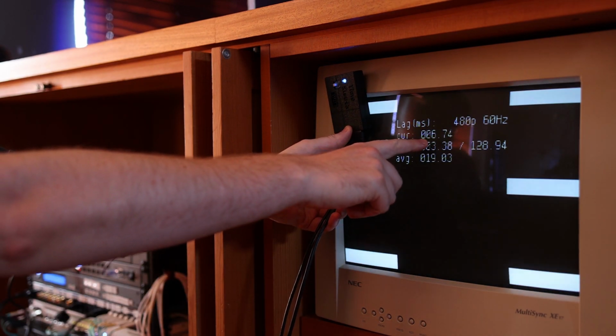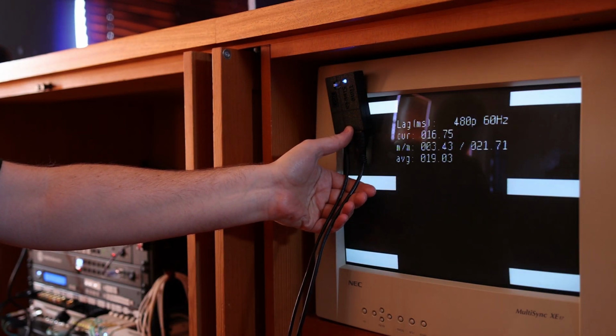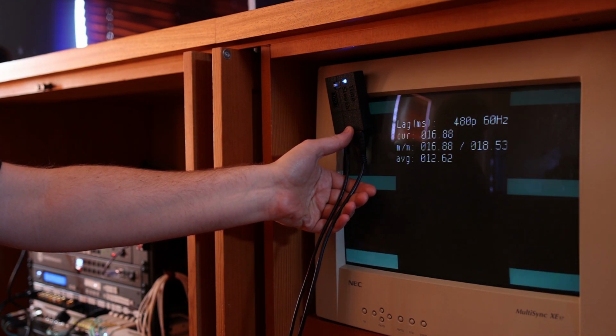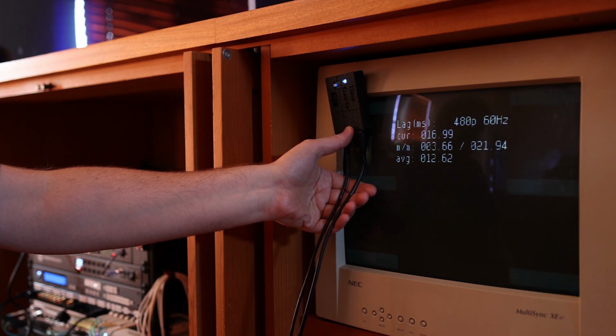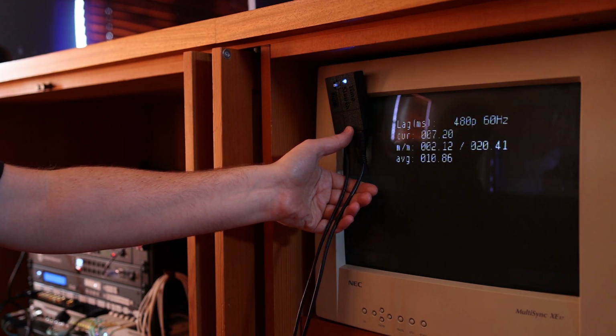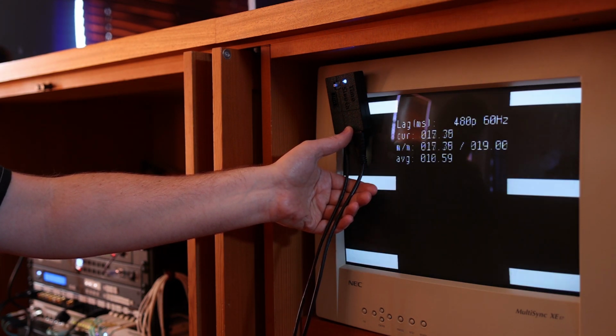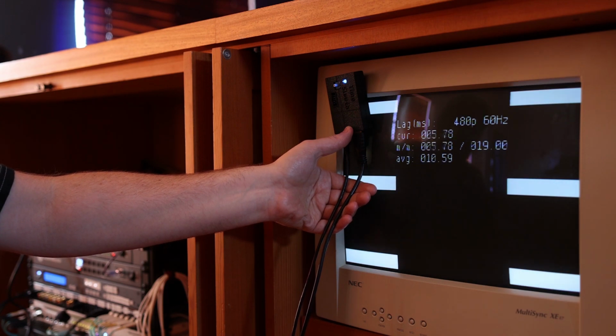If you notice this value here, all over the place, it's continuously counting down. So it turns out the VGA to SCART adapter uses a frame buffer, and it has its own clock source generator. This means that it's constantly putting out its own 60 Hz signal versus the 60 Hz signal coming in from the Time Sleuth, but both of them are at slightly different frequencies, so one may be slightly above 60, one may be slightly below 60, and because of that, the two of them don't quite synchronize up, and it simply shoves out a frame whenever it wants to.